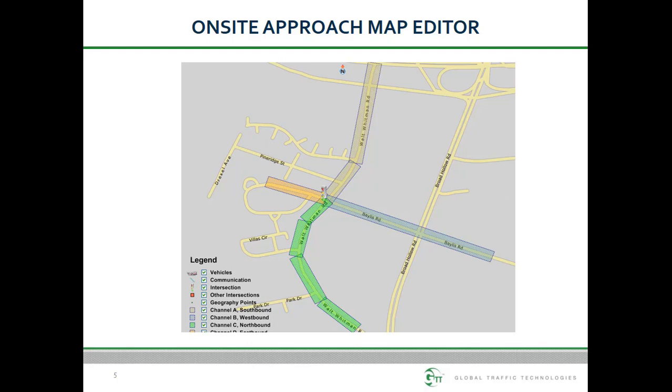If the zones are drawn too short, then the ETA and distance values used to trigger the output will not be used. The Creating Opticom GPS Approach Zones video addresses the best practices in drawing approach maps. GPS triggering points are determined by the values entered within the range settings section in ONSITE when approach map lengths are long enough. Triggering points are set using either estimated time of arrival or distance.